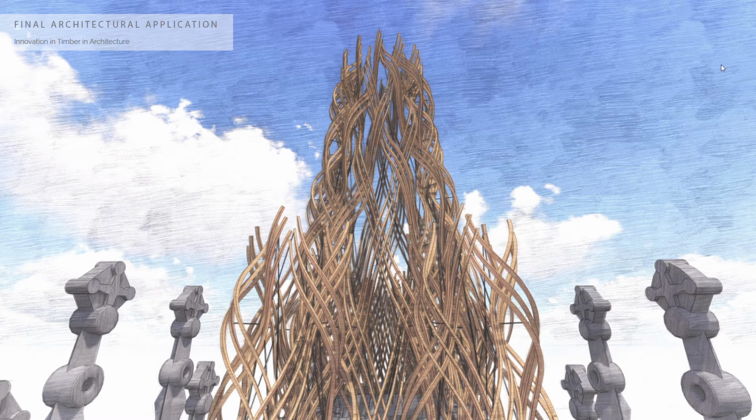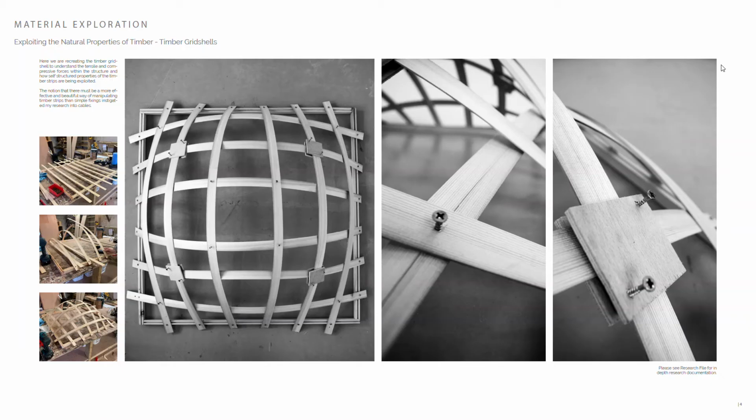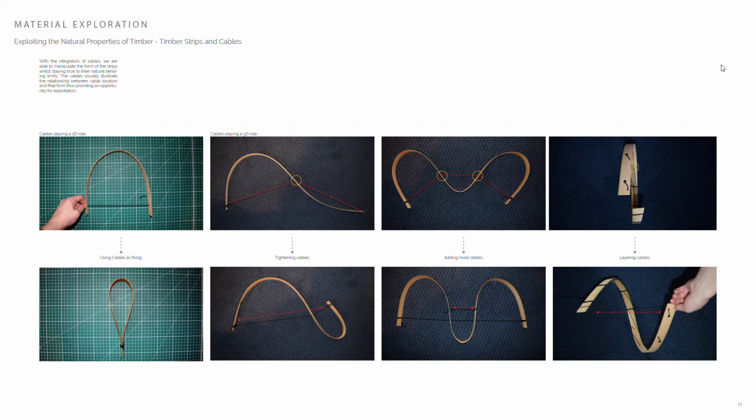So how can we utilize the natural properties of timber? A timber grid shell is a great example of how the structural properties of timber strips are being utilized. The grid shell form is created by gently bending the timber strips and fixing them in place at each intersection. The notion that there must be a more effective and beautiful way of manipulating timber strips than simple fixings instigated my research into cables. With the integration of cables, we're able to manipulate the form of the strips while staying true to their natural bending limits.